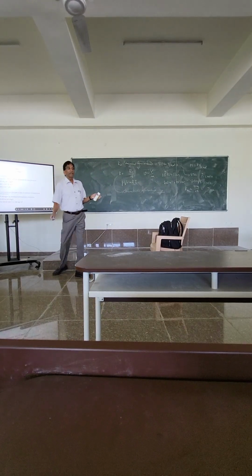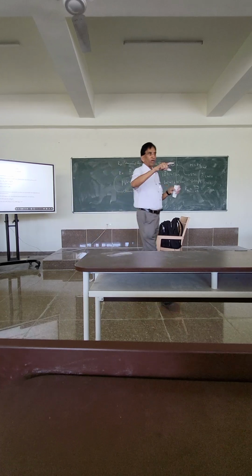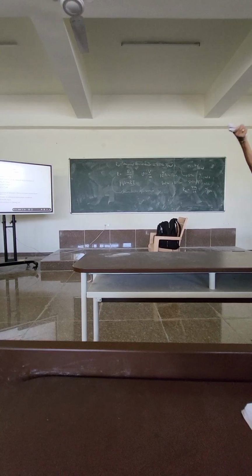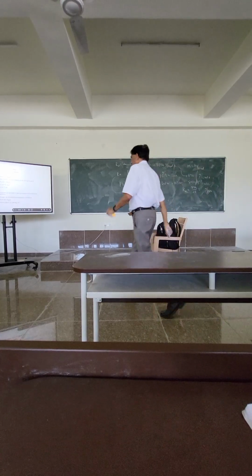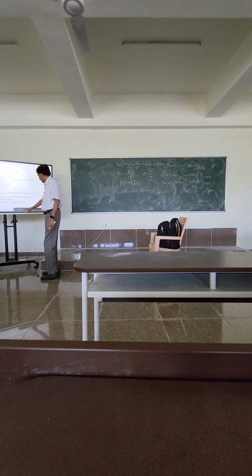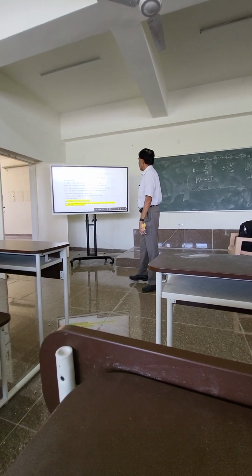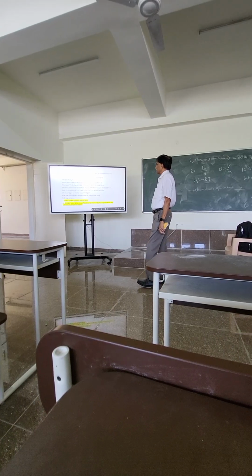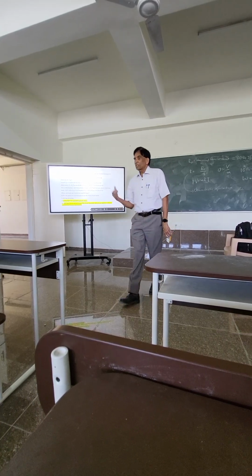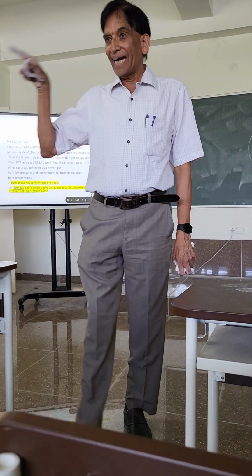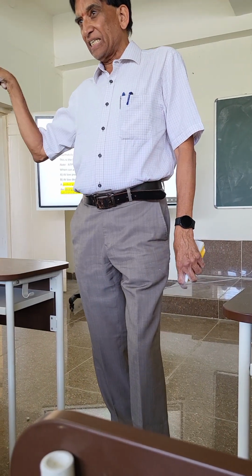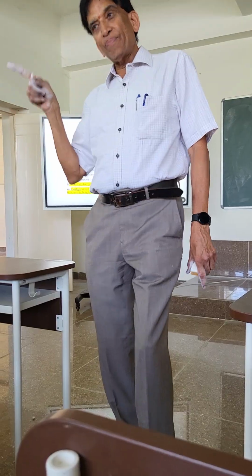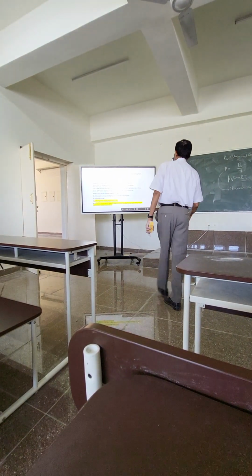Now, is this all clear? How do you calculate the density of air? This is what you develop in the lab. The calculation of Reynolds number, the Grashof number, and other things you calculate. This is basic. Example: what is the volume of 1 mole of nitrogen at normal atmospheric pressure conditions? Remember, I am not using the word standard. I told you standard is 25 degrees Celsius. Normal is 273.15 Kelvin.